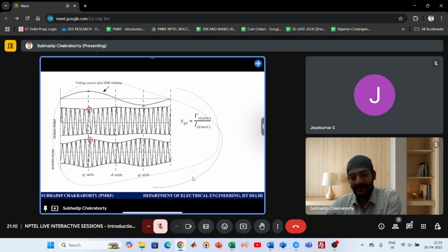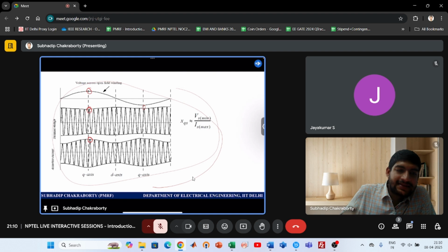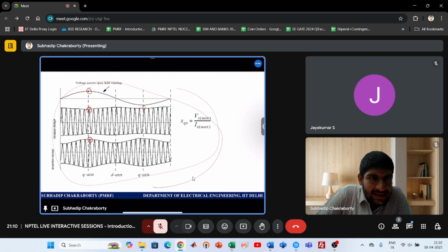See, one thing you need to understand, that once you have supply voltages, that supply voltage will power the stator coils. Now it is simply inductive in nature, but a small resistance is also there. So that will decide how much current it will take. But the amplitude of the current will depend not only on those field coil reactances, but also on the reluctance path. So that is dominantly inductance only, right? But that inductance is varying.